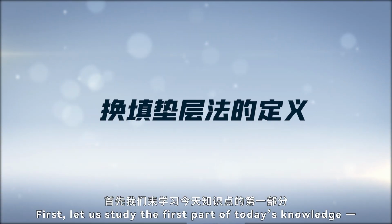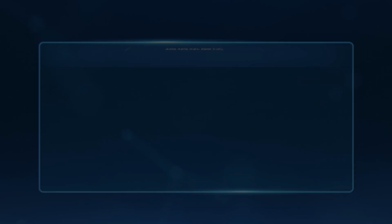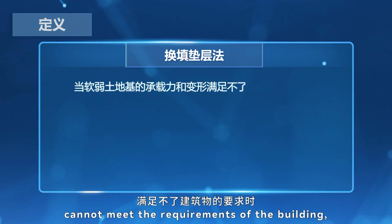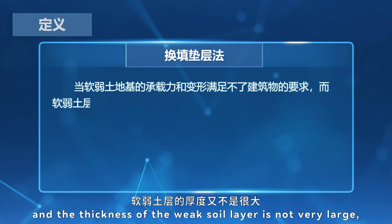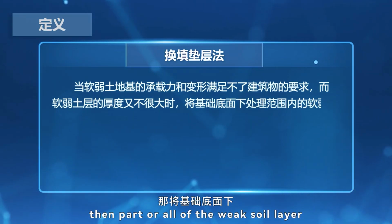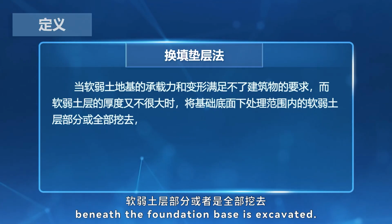First, let us study the first part of today's knowledge, the definition of the replacement fill cushion method. When the bearing capacity and the deformation of a soft clay foundation cannot meet the requirements of the building, and the thickness of the weak soil layer is not very large, then part or all of the weak soil layer within the treatment range beneath the foundation base is excavated.